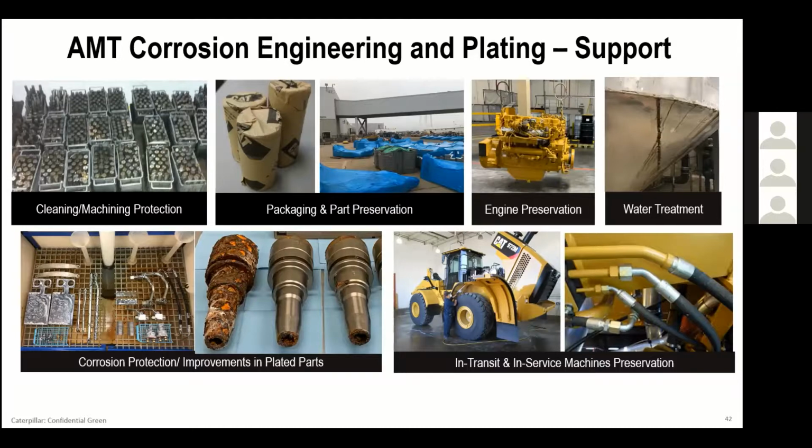And then you're looking at some pump shafts, and here we're showing the difference if you put a plating on. In this case, it was electroless nickel. So the two on the right-hand side were plated with electroless nickel. The one had no plating. If you put that into an accelerated environment, in this case a salt spray chamber, you can see the big difference, the advantage that the plated part has over something that has no protection. So those are just some of the tools.